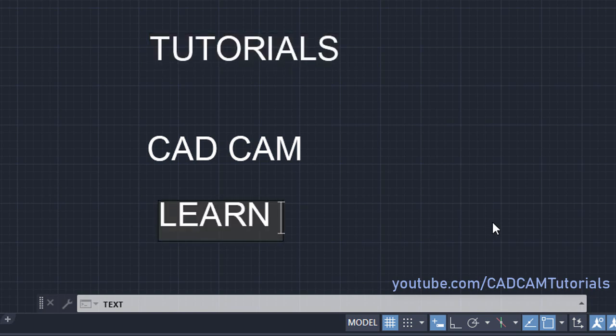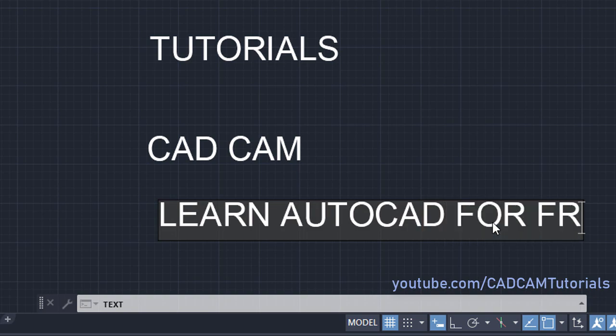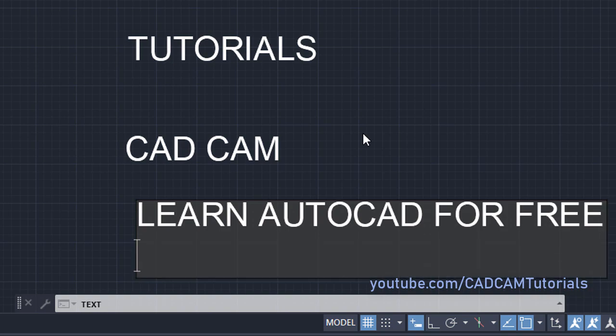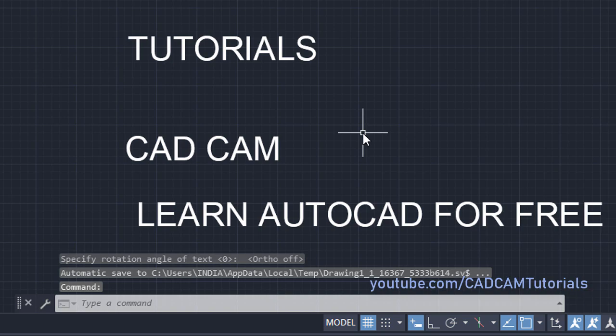Learn AutoCAD for free. Okay, once you have typed your contents, remember that you should not press escape here. If you press escape, it will get cancelled. So you always have to remember that you have to press enter and one more enter. Then only will the text command get completed.